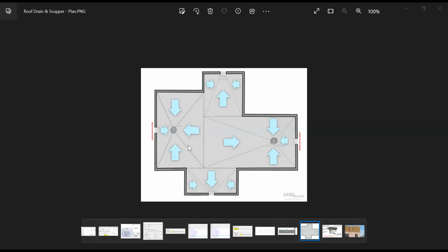Where you include these roof drains really depends on the design of the structure you're working with. It's possible that you don't have a place to bring them down, and in that case, you may use something called a scupper. We have scuppers in this plan all the way around. Sometimes the scuppers are an alert that says the roof drain has filled or is clogged and water is coming out the scupper. So you have a problem to resolve.